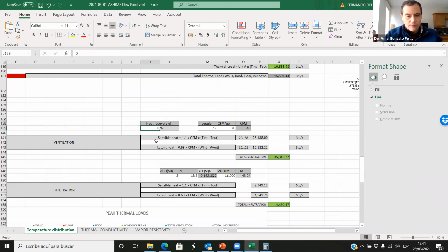But if we do have a heat recovery, that means that we have increased the efficiency of our ventilation system. So even if we have a good infiltration rate, I mean, we have 3, that means that we meet the passive house standards, that will be above this. When I was a student, they told me the 10% infiltration rate compared to the ventilation, because we didn't apply heat recoveries. So we were looking for air tightness.